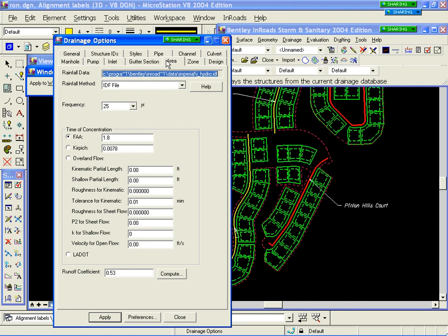And when you get to rainfall, you have the opportunity to specify an IDF curve. We'll go open one of those in a second after we do the structures.dat file. If you do not have the IDF table, then we provide the standard equation, because most of the IDF curve tables that you look up from NOAA or USGS, within the table's nomenclature, will give you the coefficients used to generate that table.